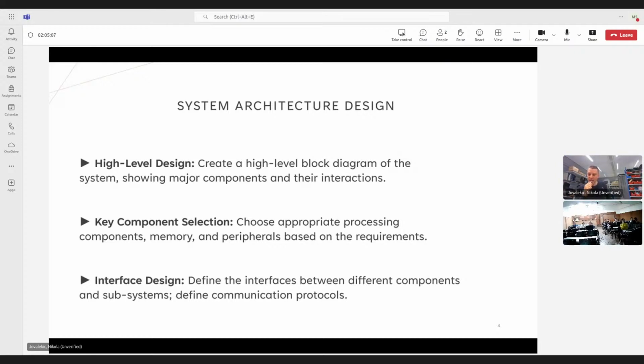Well, for example, if you have a sensor that has SPI, or a memory with an SPI bus, then you have to connect that with the CPU. Yeah, that's for example one application. How would you classify SPI, as a high-speed interconnect or a low-speed interconnect? Well, with the bandwidth of today, I'd say low speed. Low speed. Yeah, that's correct.